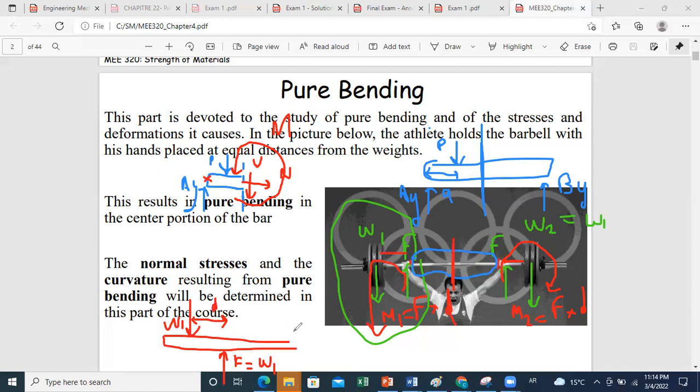Then when you do a cut at the following section, first, if you write sum of x equals 0 on your part in equilibrium, you don't have any axial load acting. This is why you don't have a normal internal force. So N is 0. Now concerning the shear, the convention for shear is to be positive downward here.